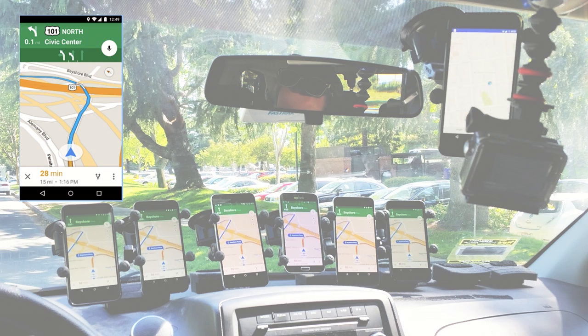We use a military-grade inertial navigation system that provides centimeter-level accuracy in order to collect ground truth location for comparison. We also take video imagery to compare position jumps and lags when all devices are in navigation mode. This gives us the automated ability to count and measure each device's position jump or lag, and then produce a report listing the exact moment when a device experienced these lags and jumps.